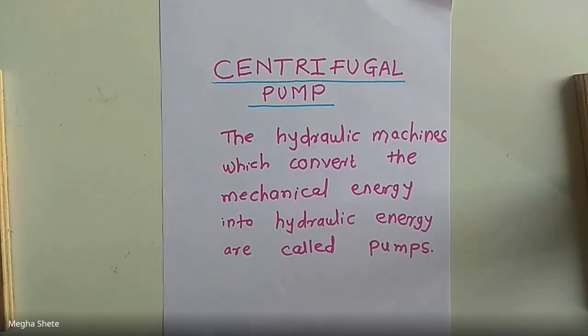Centrifugal pump acts as reverse of a radial flow turbine. The flow in the centrifugal pump is in the radial outward direction. The centrifugal pump works on the principle of forced vortex flow, which means that when a certain mass of fluid is rotated by an external torque, the rise in pressure head of the rotating liquid takes place. The rise in the pressure head at any point of rotating liquid is proportional to the square of the tangential velocity of the liquid at that point.